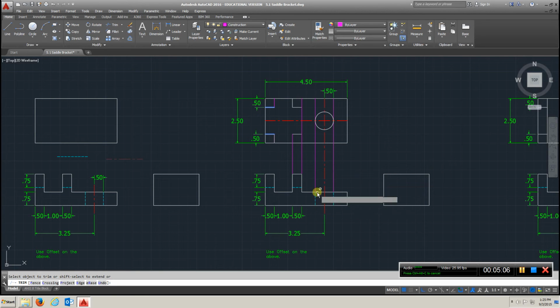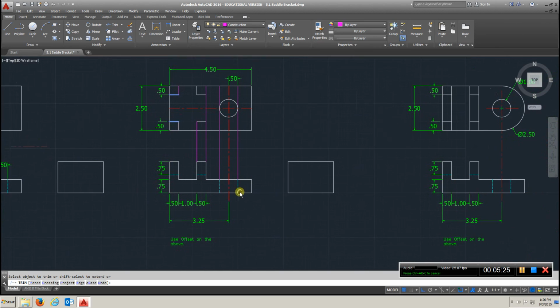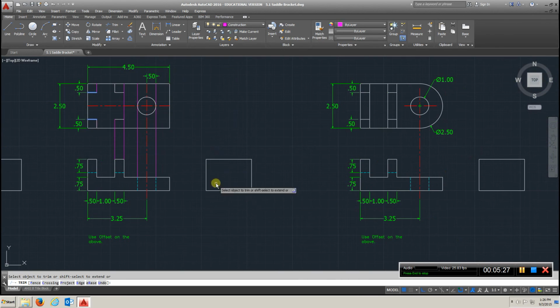Same thing, I just transferred the line straight up, and the overall part is 2.5. I offset this 1.25 and got my center mark and put a 1/2 inch radius hole in here. And moving forward, trim everything off until you get the top view looking like this.